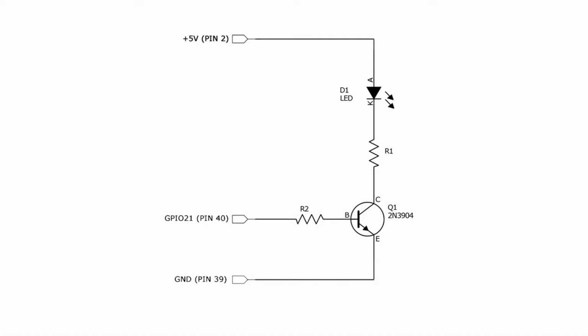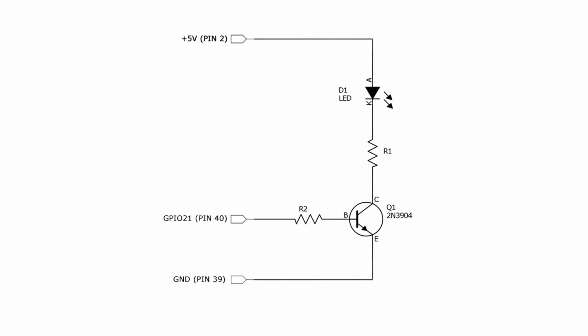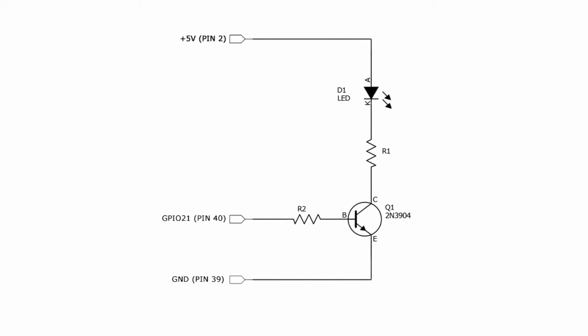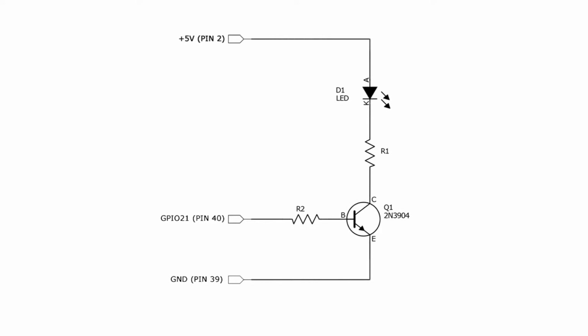Next, let's look at a little different circuit. In this case, I have a Blacklight LED that has a forward voltage drop of approximately 3.4 volts. And I'd like to drive this one at 20 milliamps because I want it to be much brighter. The problem is we can't use a GPIO port pin directly because of the higher current and the voltage is higher than the port pin is capable of supplying.